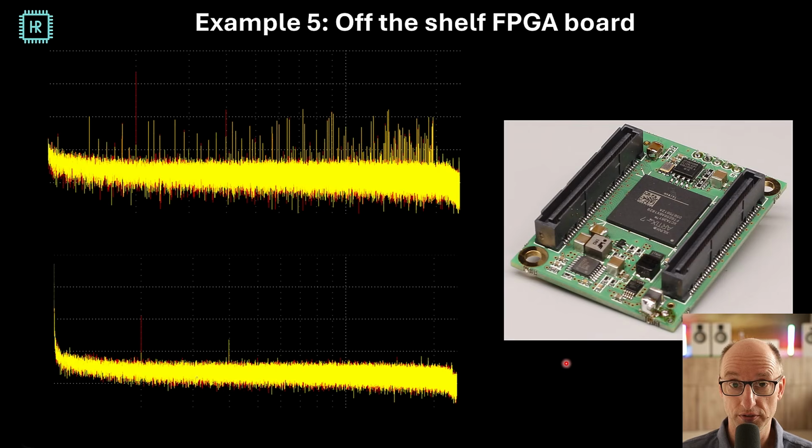What made it very hard is that if I would have chosen a 6 or 8 layer with buried vias and things like that, or micro vias, this board would have been a piece of cake to make. However, that's extremely expensive. So I wanted to stick to a standard 4-layer standard process. And then I discovered it's extremely hard to get the power routing and the ground routing good enough.